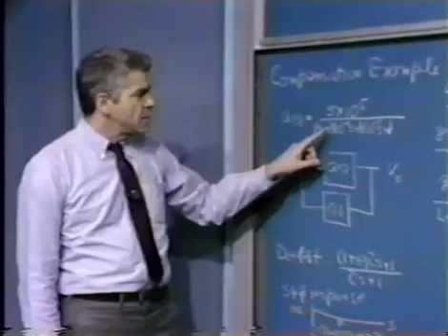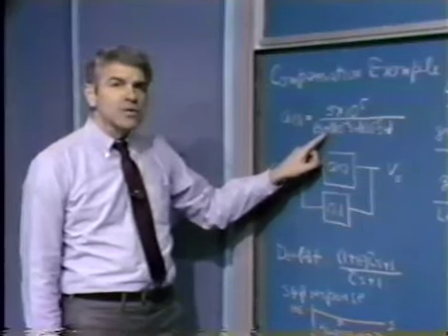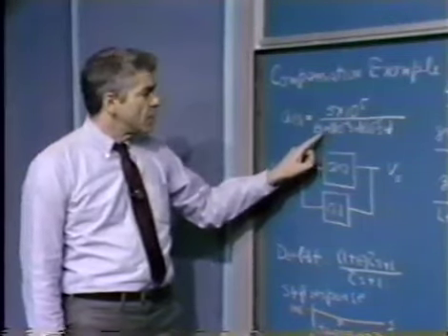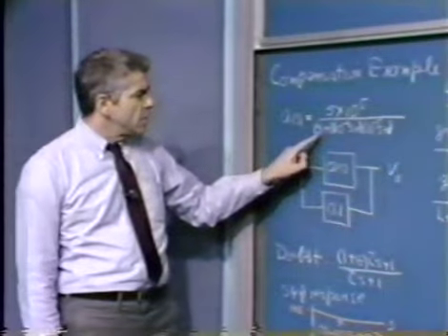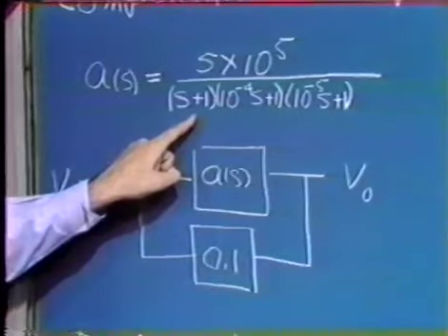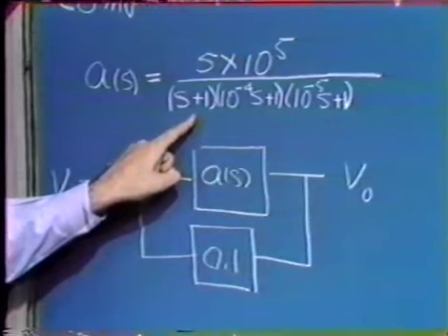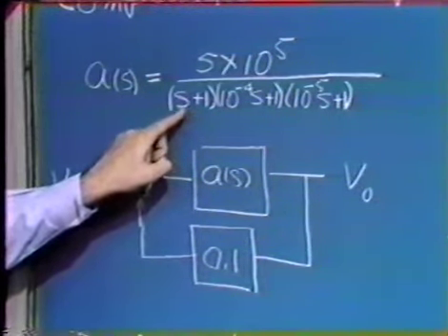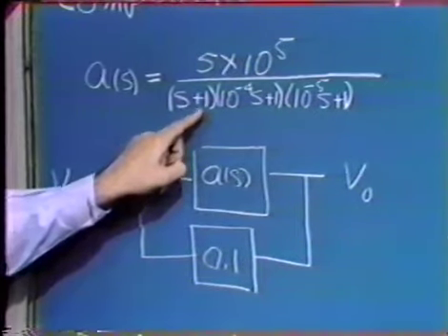You see, when you design this sort of an amplifier, or in fact when you design many mechanical systems, servo mechanisms, you try to dominate the loop transmission with a single low frequency pole. We've looked at that method of stabilizing a feedback system before. And so many, many systems of interest have a dominant pole.